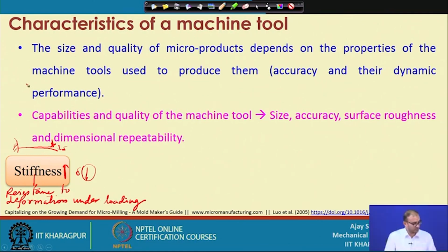That is why stiffness is more important, because we have a physical contact between the tool and workpiece. So, our workpiece is here, and we have a tool which is moving in this direction with a depth of cut inside. Basically you want to remove material from this part. So, this much physical resistance is also provided by the workpiece, and the tool is also providing enough force. Under this particular condition, how much is the stiffness? Suppose you want to move from here to here, whether you are exactly cutting in the same direction or your workpiece is bent in this direction, and sometimes the tool is also coming out of this direction. That is decided by the stiffness of the different components of the machine tool.